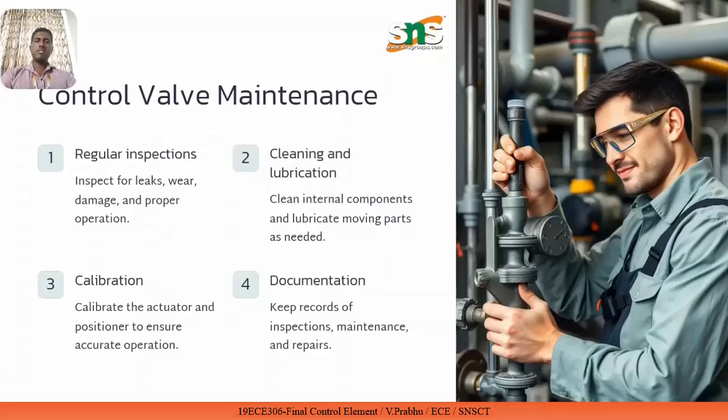So in case of periodic maintenance, the first thing is regular inspection. Daily, a technician has to inspect for any leakages from the gland packings, any visual wear and damage, and whether the valve stem is moving properly and freely. So these are the regular visual inspections.